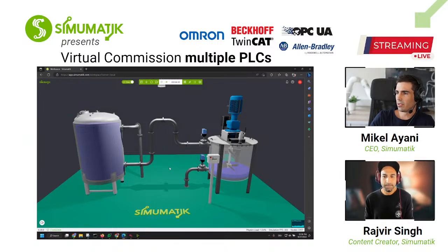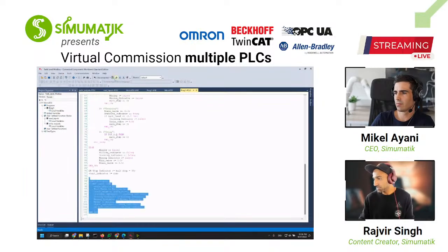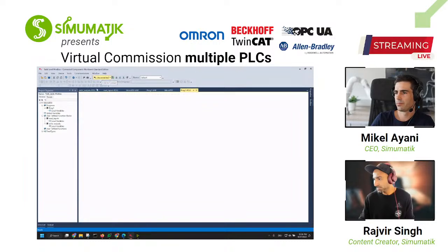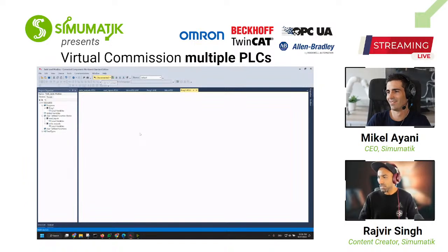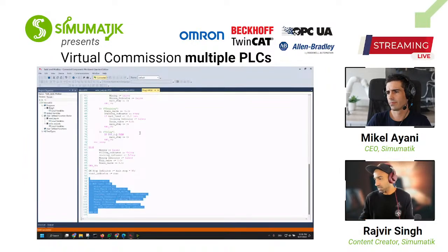How is the debugging in CCW? So can you see the online values easily? Yes, you can see. I can go online. You have to be a bit patient with this PLC because it's not the fastest one when it comes to CCW. So you can see I click online. It takes a few seconds. But yeah, the software is free to use and has a free simulator, which is easy for students to start learning if they don't have a real PLC.